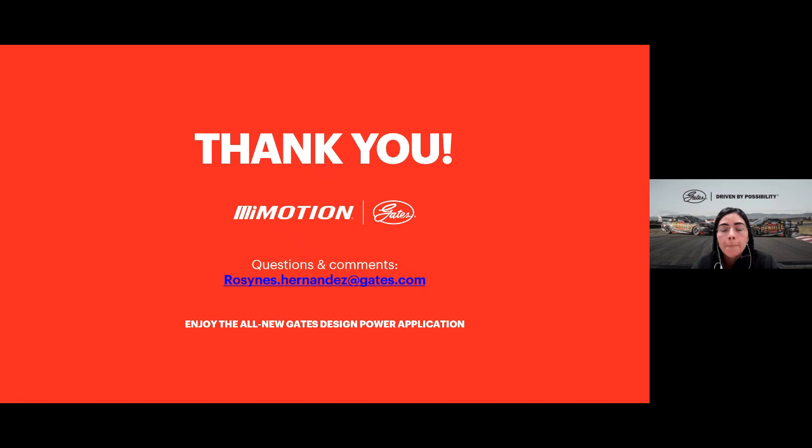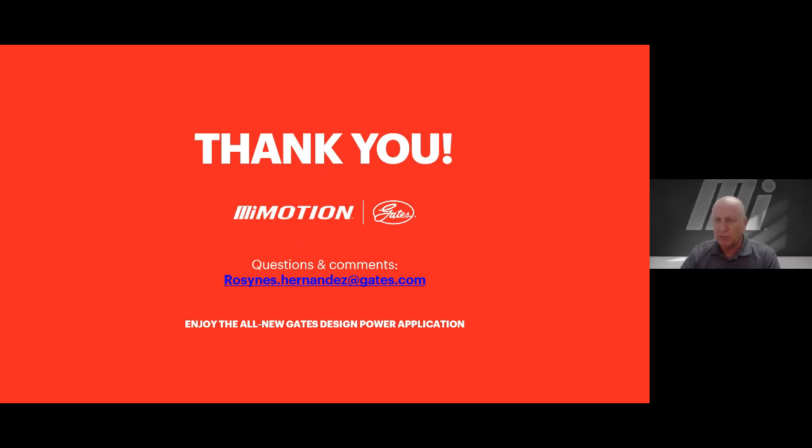The program also gives you the ability to look at the number of hours design life, I noticed. So if we know that the current belt's only lasting 500 hours, and they want to get 15,000 hours, well, then you could adjust the program and put in the appropriate belt to give it that extra life.